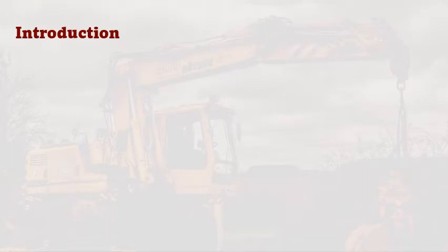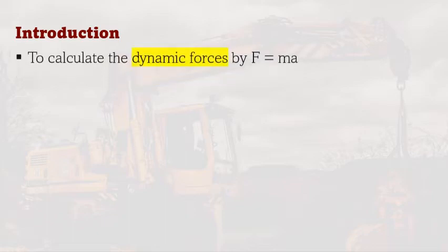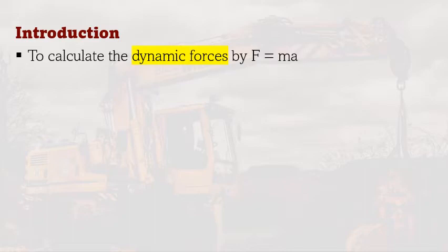Maybe right now you are asking what's the importance of acceleration analysis. With the advent of high-speed machines, the accelerations of the moving parts are becoming more important. The inertia forces produced by the accelerations of the links in a machine may be of a high magnitude, and in some cases, at a certain position, may be higher than the forces produced by the working medium.